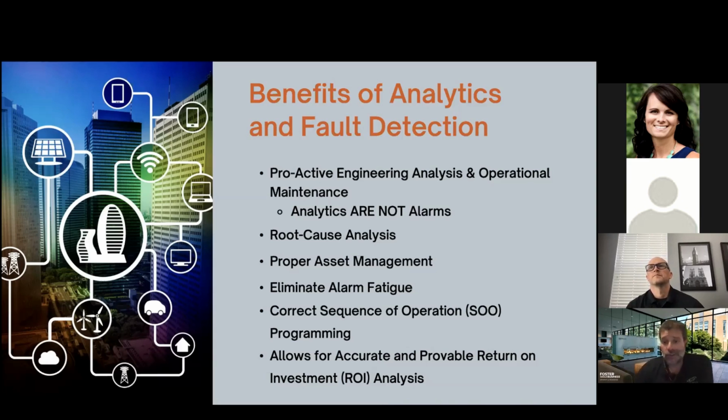Yeah, I mean, you can use it in ORs, right? We talk about pressurization, how important that's been recently in the hospital systems. You can look at the pressurization of spaces and watch that over time, and you can see when it's winning and when it's losing and make those modifications, and they'll validate your sequence of operations.